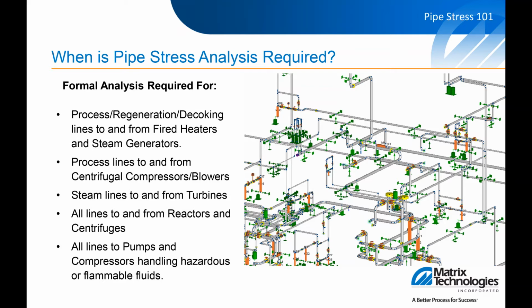And formal analysis is going to be, you're going to put it into the software, you're going to look at all aspects of the system, flanges, connections, thermal growth of equipment. Because these are sensitive pieces of equipment, they're high risk items. Not only if you damage the equipment, but if you have a leak with these flammable or hazardous fluids, there's going to be a problem. So there's a high level of care implied.